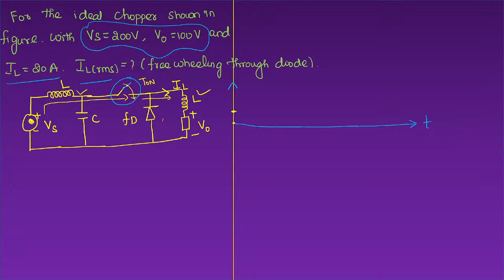Through this inductor, and then this inductor, like this, it will be going like this, because this positive voltage... anyway, this inductor will be short circuited within a few nanoseconds or microseconds, because we know when an inductor is connected with the DC supply, instantly it will not accept, but within some time, slowly it will start behaving as a short circuited one. So directly we can bring the relation between input and output voltage.